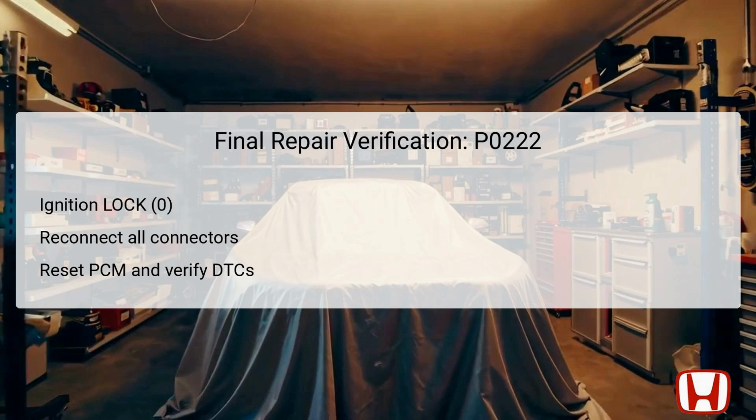If P0222 reappears, further investigation is warranted, focusing on loose connections or the integrity of the PCM. If no issues are detected, the troubleshooting process is complete.